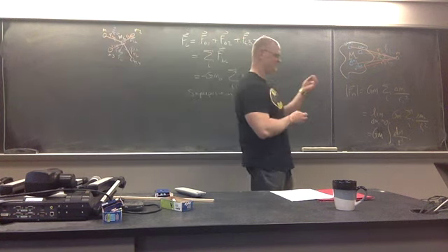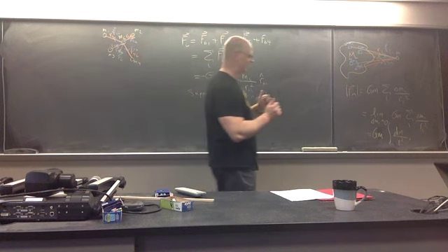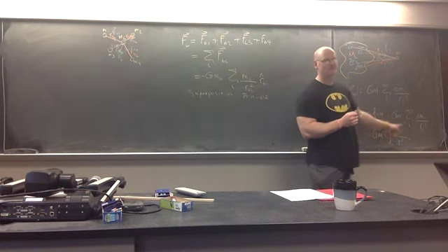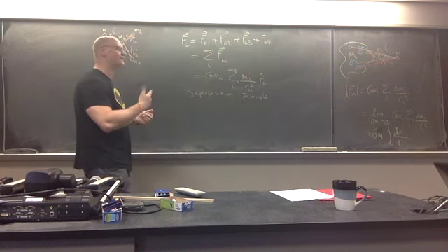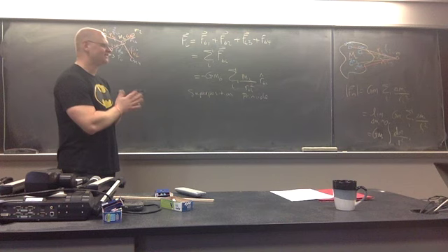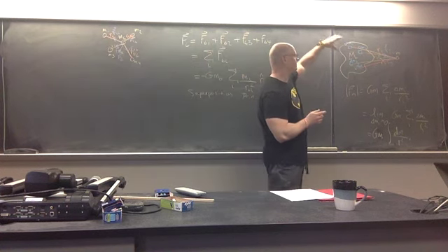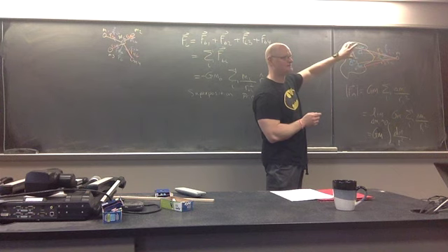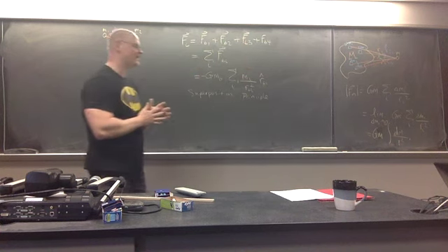Now, we talked about this before when we talked about moments of inertia, but to integrate over a mass is kind of a strange statement. So typically what we're going to do is exactly what we did then, where we turn this dm into a geometry integral instead of a dm integral. So, integral over the mass. Depending on the type of symmetry that we have, dm will either become lambda times dl, eta dA, or rho dV, depending on what type of geometry the system has.